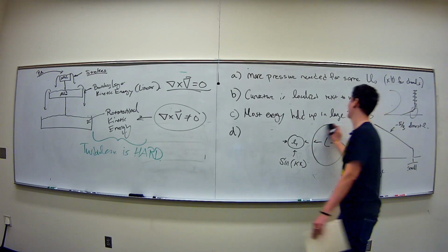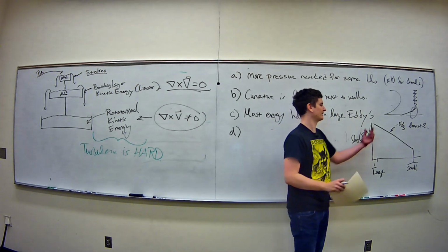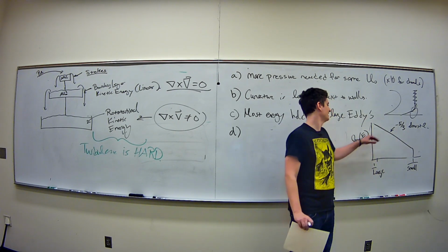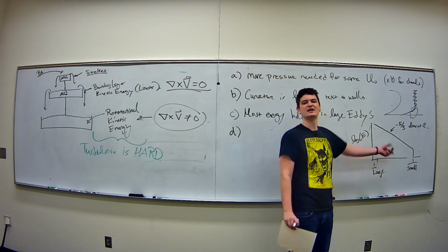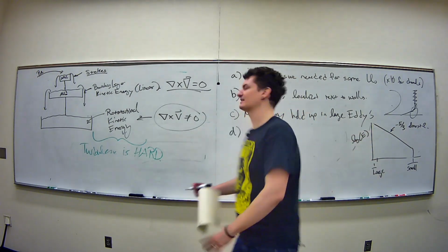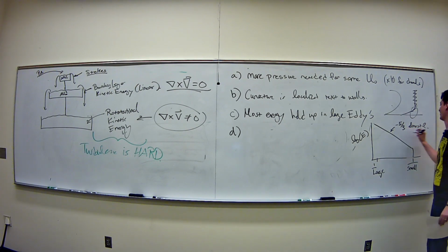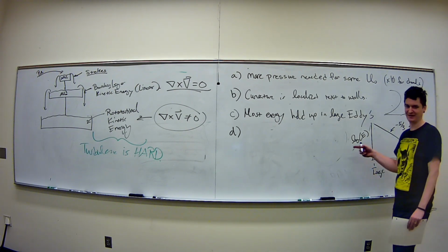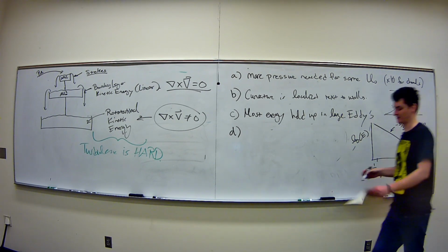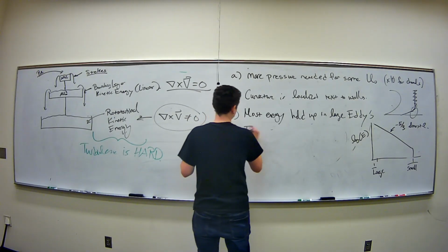So the energy cascade's saying, well, the energy is mostly going to be held up in that large rotating eddy. And as I go smaller and smaller in eddy length scales, there's a one-to-one correspondence of how much energy is associated to that eddy. A lot to digest. The idea is you have this plot in mind. And the weirdest thing is that the slope is almost -2. So turbulence has a fundamental thing where it's almost even numbers, it seems like, all the time. So that's the wave number, and that's E.